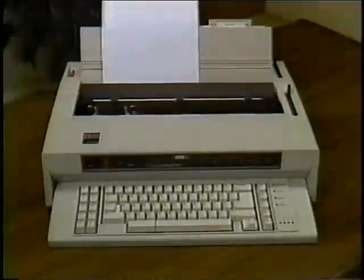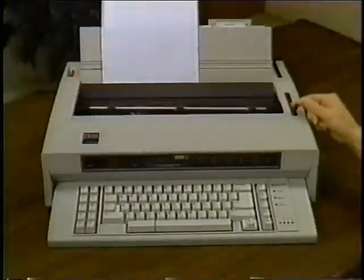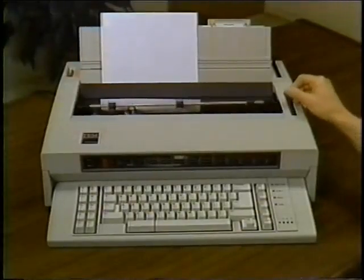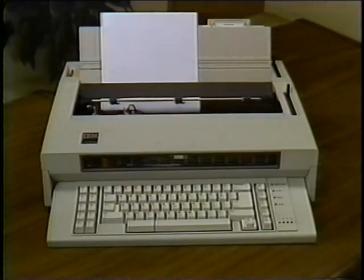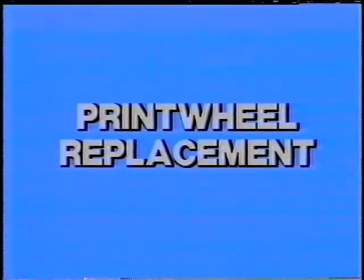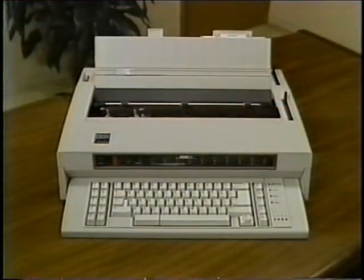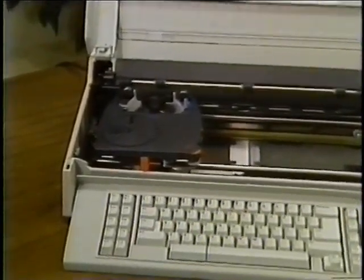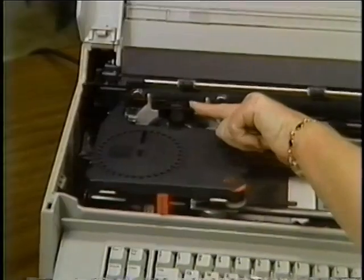This machine has a semi-automatic paper insertion feature. Push the paper bale load lever all the way forward. When the semi-automatic paper insertion activates, the machine will position the paper so the first writing line is 1 inch below the top edge of the paper. To remove the print wheel, pull back on the print hammer and lift the print wheel straight up.